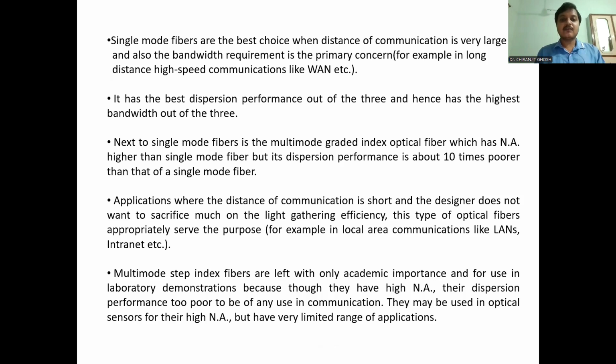Next to single mode step index fiber is the multimode graded index fiber. As I told, the multimode graded index fiber is better than multimode step index fiber, but obviously it will not be as great as a single mode fiber. So it is in between the multimode step index and the single mode step index. And of course, multimode step index fiber is not used for communication. It's only used for some kind of sensors.